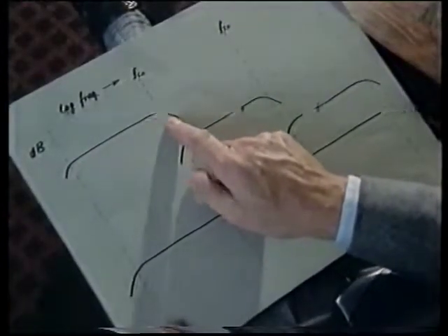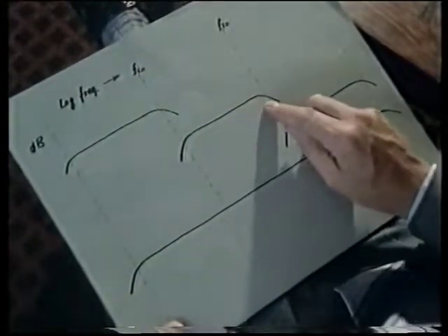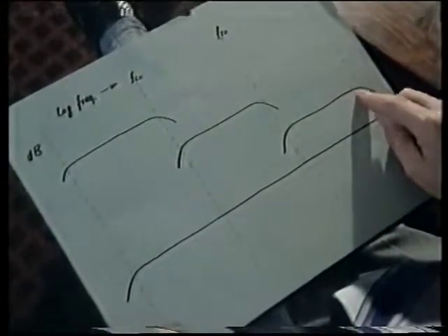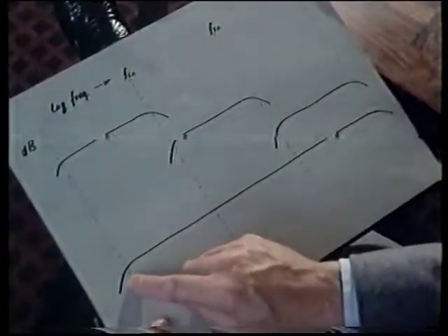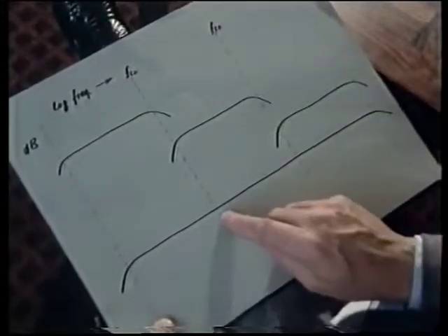A typical arrangement using 3 loudspeakers might, for instance, look like this. We'd have a low-frequency loudspeaker covering preferably not more than a decade, a medium-frequency loudspeaker also handling about a decade, and a high-frequency loudspeaker which carries the response on to the limits of audibility. The trick is to marry these together with suitable filters in such a way as to produce a continuous collinear frequency response without the joints being audible.